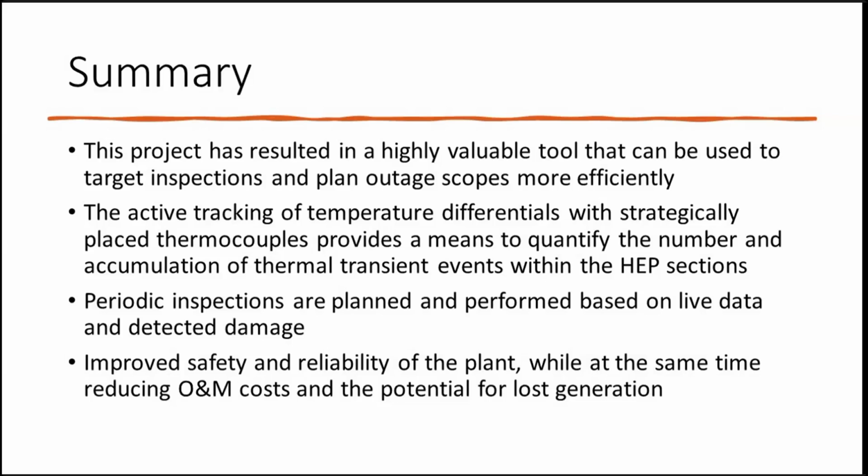Yeah, so certainly you can implement it midlife. I would say most people are at the point of implementing it midlife. The challenge is always doing the backward look: how much damage did we accumulate prior to this, or what events might we have had previously? And there's always going to be some level of uncertainty there. That's why we try to pair it with inspections. But certainly getting monitoring installed is going to give you a lot of value on its own going forward to identify when you're having events. So it can be midlife.